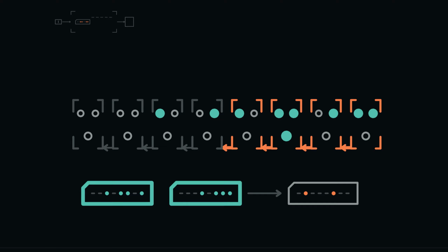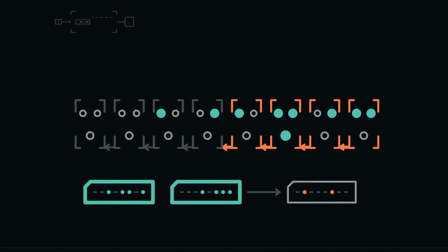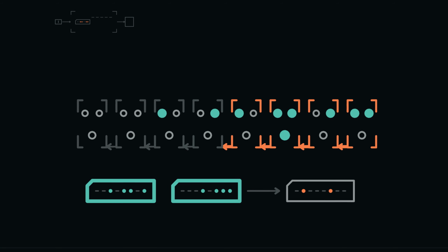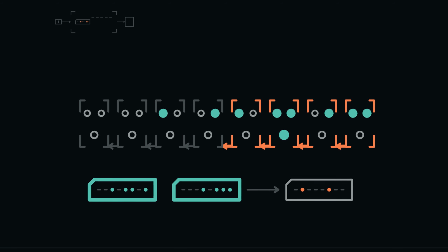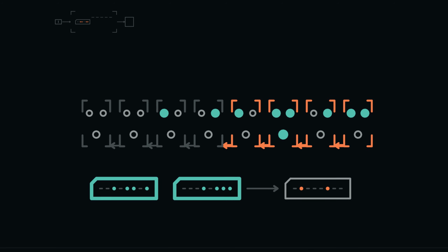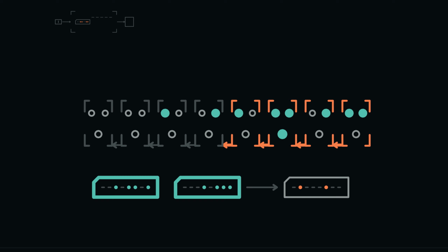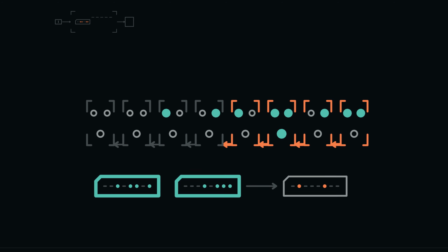Place 8 full adder cells in bit order. Position 0 receives carry in 0. Its carry out connects only to carry in 1. That carry out connects to position 2, continuing toward the highest weight. This is an 8-bit ripple carry adder.